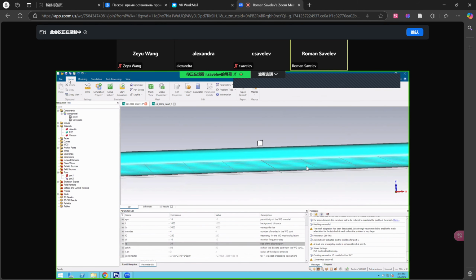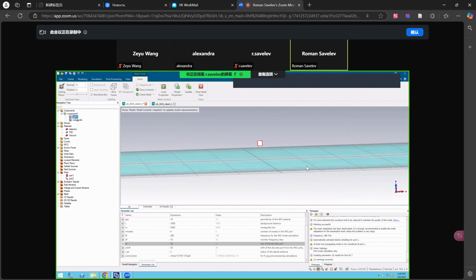For instance, open Home tab, click Mesh View. Then choose this list of components, list of objects. Choose this brick. See, there is an option, Local Mesh Properties. So open this Local Properties.